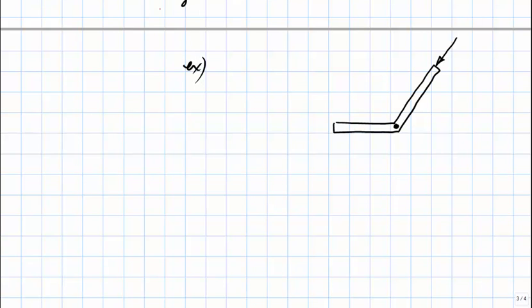In fact, we can indicate this by drawing the line of action. That's the force's line of action, of course, and the force is directed right along this line, which passes right through the center of rotation. Therefore, the torque associated with this force equals 0. If we call this force F, then the torque produced by that force must equal 0. Again, the force doesn't equal 0, but the torque does equal 0.